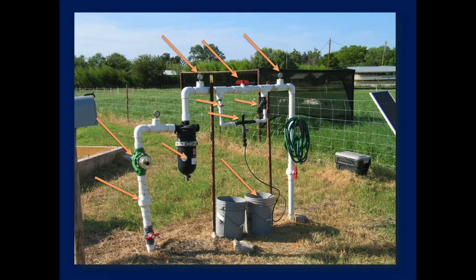The next thing is, here is the Mozzie. Here's the bucket of fertilizer that we want to put out. This is a cutoff valve, and again, the Mozzie. And what you do is you've got a pressure gauge here and a pressure gauge here, and you turn the water on, and you start closing that valve, and as soon as you get about a 10% difference in pressure between the high side and the low side, the Mozzie injector will begin working. And as long as the flow rate is constant, it'll work just fine.